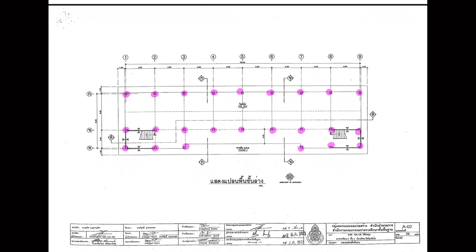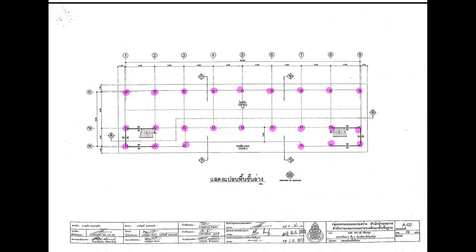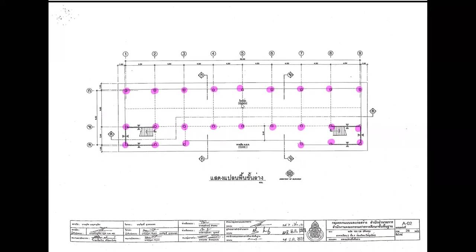Then the ground floor. Generally, we don't use steel for the ground floor. You know why? Oh, nobody answers me. It's because of the exposure, because on the ground floor, of course, you have the soil condition and so on. In terms of humidity and the water content, it's not friendly for steel. So generally, we don't use steel for the ground floor. We rather use concrete to protect against moisture and those kinds of things.